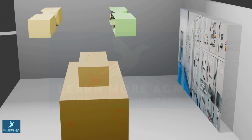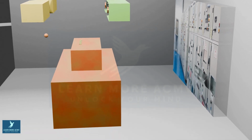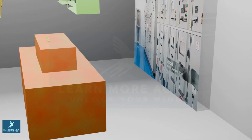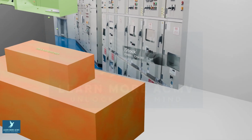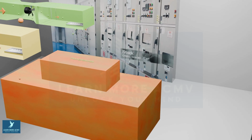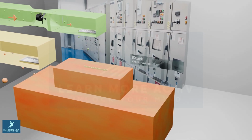In a building, a ventilation system is installed to remove hot air from electrical equipment rooms. When the equipment operates, the electrical panels generate heat, warming and moving the air around them. To control this temperature rise, a fresh air fan brings in cooler outside air, while an exhaust fan pushes the hot air out. This cycle continues until the room temperature reaches the required design level.